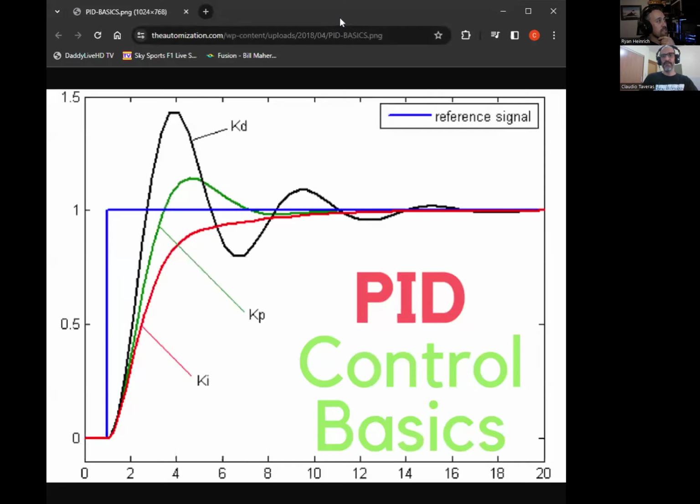So here, I'll throw up a little graphic so you can correlate your explanation. There it is. So right here in black would be an overshot target. So that's the P value being too high. And it probably only passes using over P. And then this integral where it's passing over, it actually could be using I because it's continuing to overshoot.